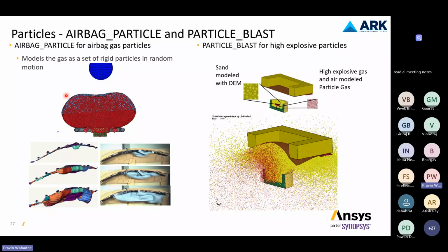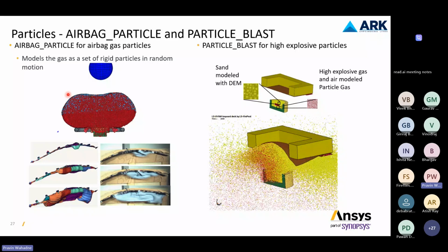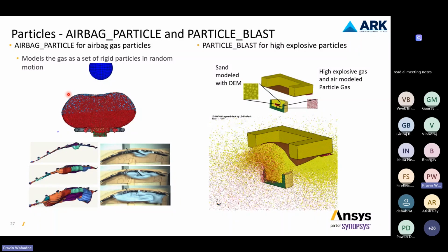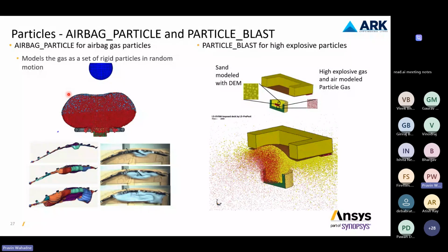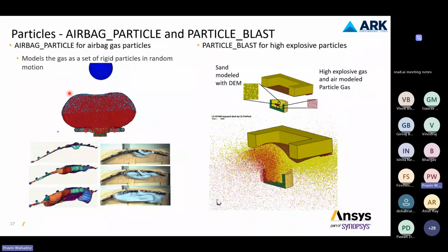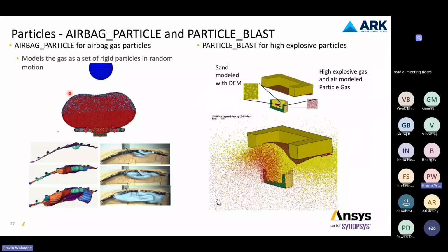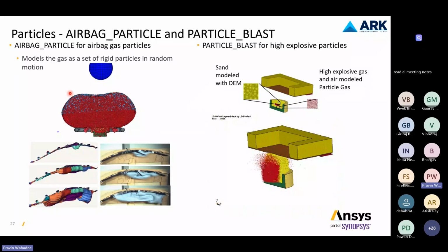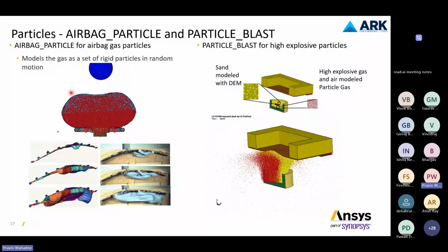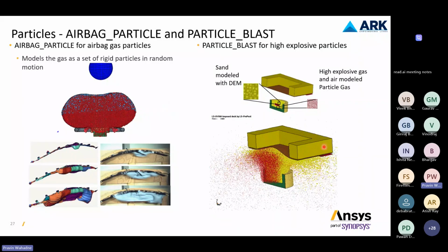To model a gas that you can inflate in a particular time period in any volume, you can use airbag particle. Similarly, if you want to model explosive particles, we have the particle blast simulation technique where you can model sand with the DEM approach, and you can also model explosive gas and air particle models with this approach.